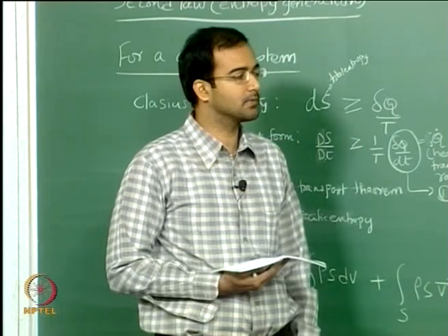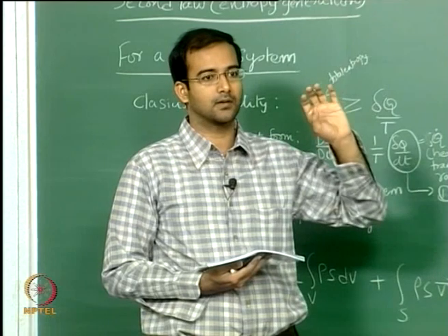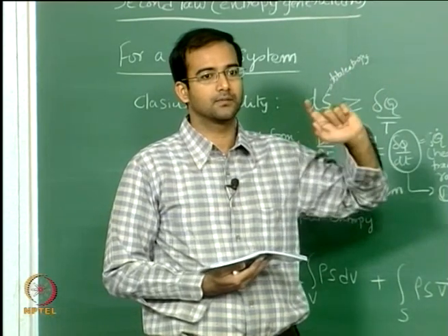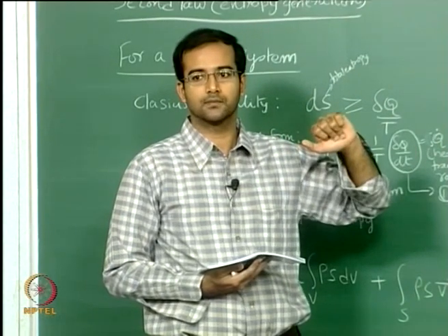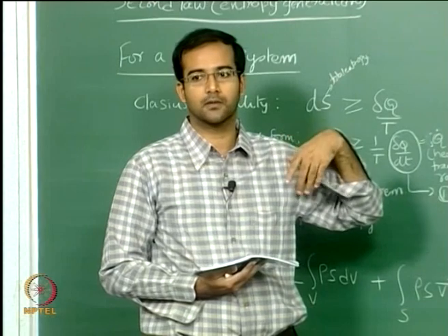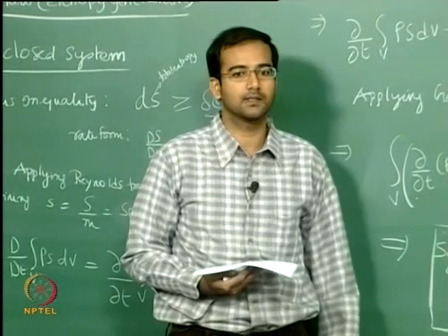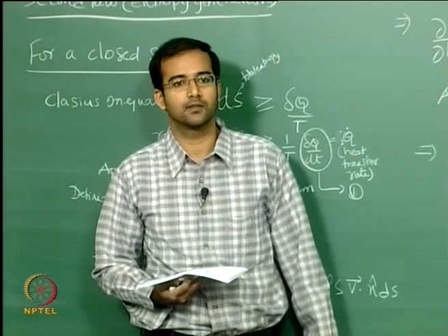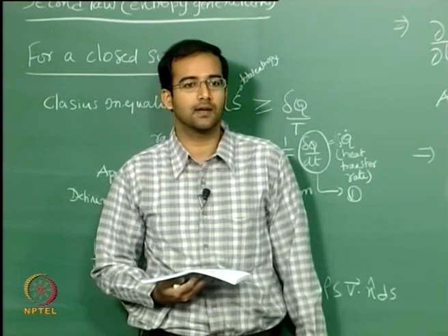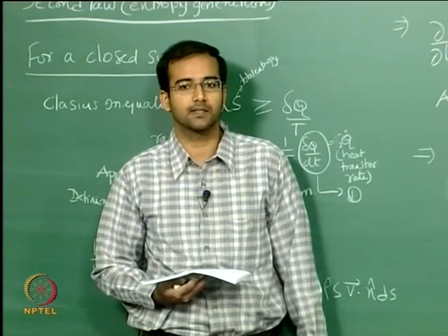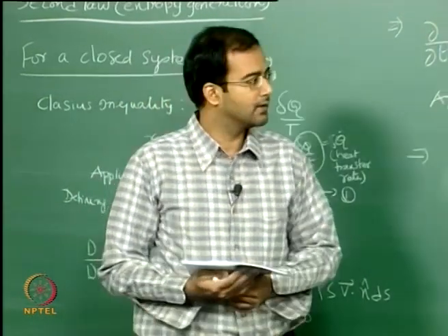So for 2D incompressible, if you solve the Navier-Stokes, we need equations for u, v and p. And if you are solving energy, again temperature. Now we don't have a separate equation for pressure. We have equations for u and v and the continuity equation, which is like a default equation. So numerically there are some techniques to overcome this hurdle, where we construct an artificial pressure equation and things like that.